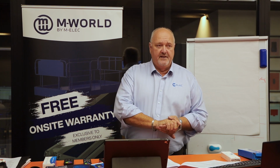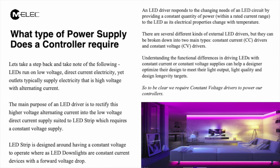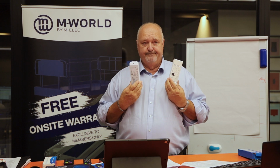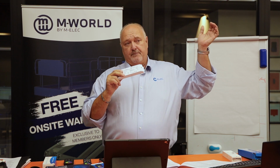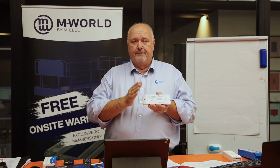We basically just went through this. What type of power supply does a controller require? When we're looking at any of these controllers here, they're constant voltage. Basically, you just want to maintain the voltage in, and the voltage out allows the strip to be maintained and a constant light level coming out of the strip. We have to be mindful of voltage drop because now we've got something in the middle, so voltage drop can take effect between the power supply, the controller and the LED strip. So we have to be mindful of the distances and the type of cable that we're using to ensure that we don't have any voltage drop issues.